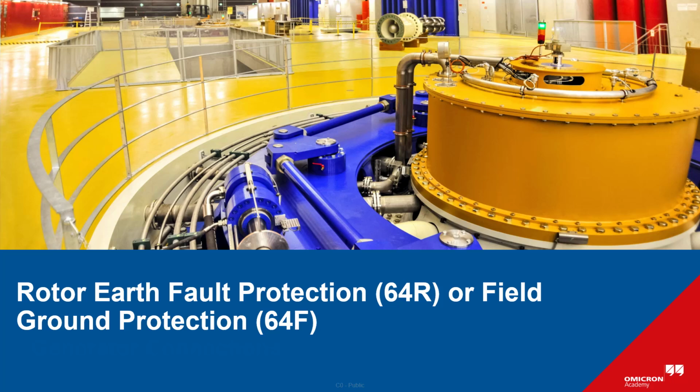In this video, we will discuss the rotor earth fault protection, or the field ground protection, identified as 64R or 64F in the ANSI code. This function detects insulation failure in the excitation circuit of synchronous machines. Since the rotor is normally ungrounded, a single fault may go unnoticed, but a second fault can cause a short circuit leading to severe vibration and mechanical damage.